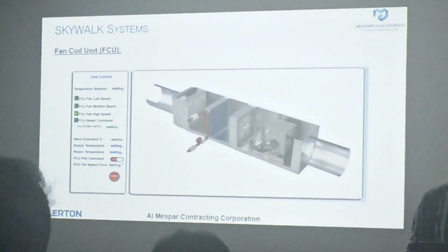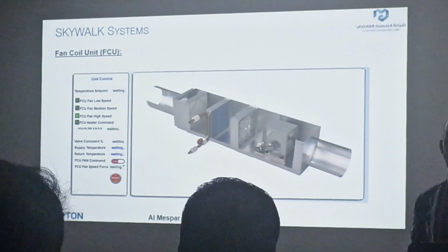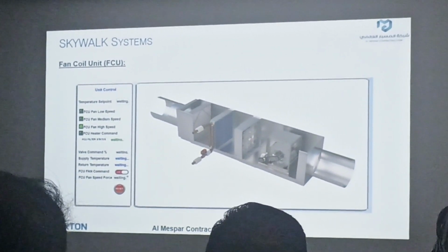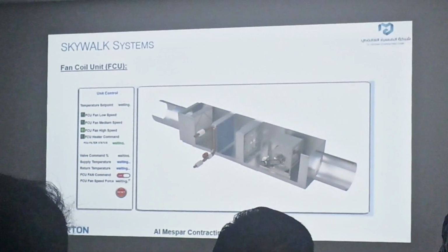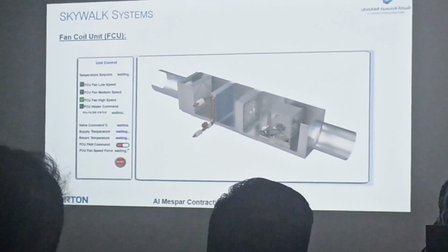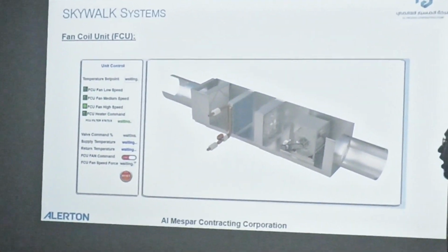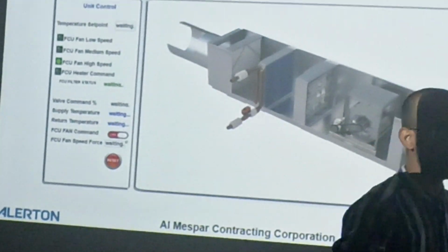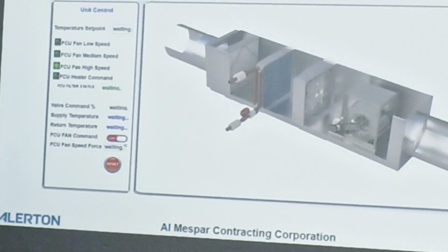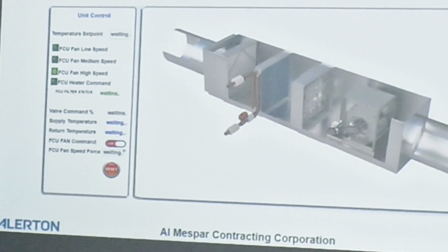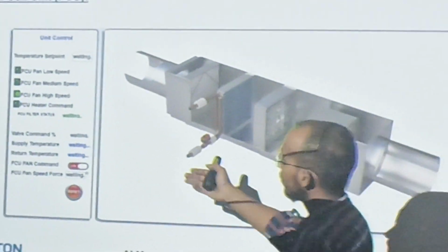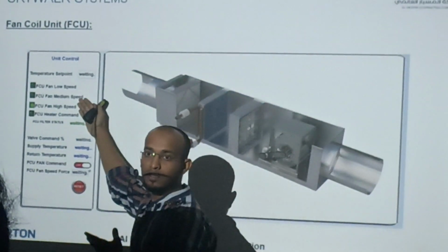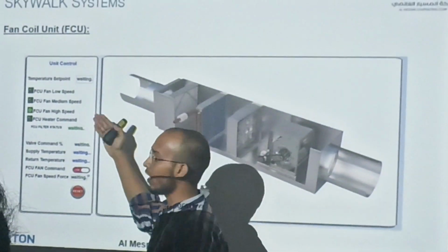Do you know what is FCU? What does it do? It's fan coil unit. It will supply the air to the skywalk. Typically it depends on the equipment. For example, we have 3-speed FCU. Somewhere it depends on the single speed. If the 3-phase motor is available, it will be single speed. Now we are using 3-speed FCUs: speed 1, 2, and 3. The command points 1, 2 and 3: 1 represents low, 2 medium, and 3 high.